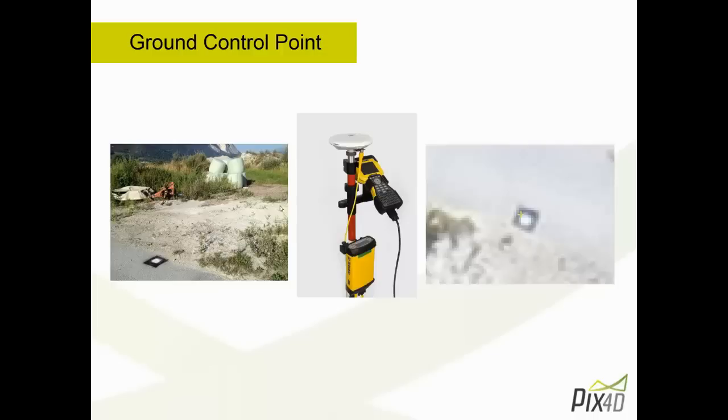However, it's a bit broader than that. You can actually also use any type of feature which is easy to recognize on the ground, such as a building edge or roof. The only thing is it has to be significantly recognizable in the images, because as you can see in this example, it's very easy to see on the left when you take it from the ground, but at 100-meter altitude from a drone, it looks a bit different. So I would advise choosing something with very high contrast.